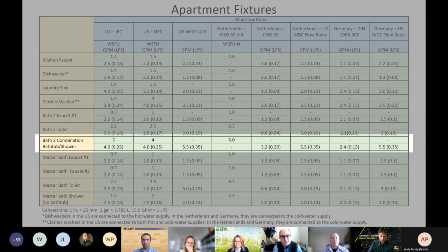That range for the valves I measured is 60 to 80%. So 0.75 is right in the ballpark. You could put 0.8 in so that you have some safety factor. But anyway, I think there are some interesting features about how to use the water demand calculator based on real measurements of those shower valves that we ought to be using as we go forward.